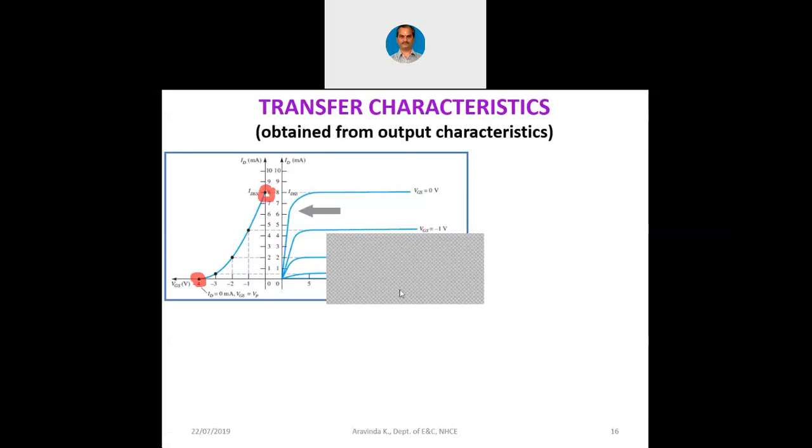You can see that in the transfer curve, y-axis is output and x-axis is input. And it is also called as transconductance. If at all we have a formula where IDSS divided by VGS, then it is current by voltage. That is called as conductance. As it is a transfer curve, we can call the slope of this curve as transconductance, because it is current divided by voltage.